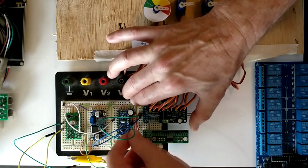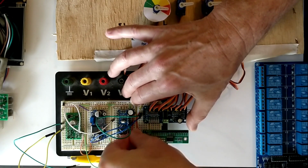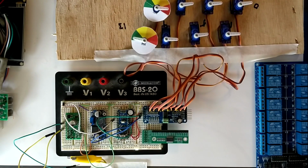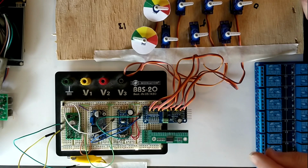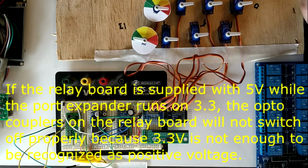I could supply it with 3.3 or 5 volts, both would actually work, but it needs to be the same voltage as we are going to use on the relay board. The relay board would actually also work with 3.3 and 5. The important thing is we need to select the same voltage for the relay board and the I/O port expander, otherwise there will be some difficulties with controlling the I/Os.